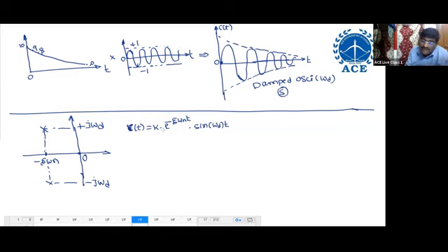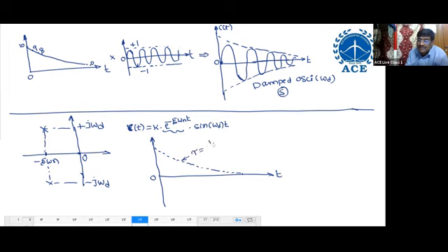First you have to draw the response for the real part. What is the response for the real part? Exponential decay. Draw it like that; I already explained all these things. It decays with the time constant of 1 by zeta omega n seconds and reaches the steady state by 5 tau. Then fold with respect to 0, so the same envelope appears below 0.